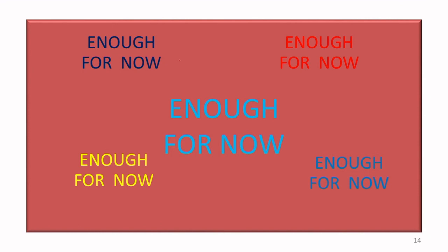In the next session, we focus on solving the wave equation to find the longitudinal components, that is Ez and Hz. Once Ez and Hz are available, they can be substituted in the expressions which we have derived here for Hx, Hy, Ex, Ey to find the fields that are part of wave motion inside the waveguide. Enough.